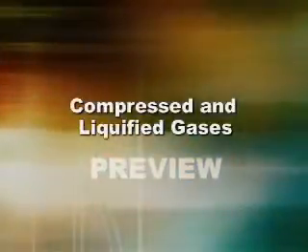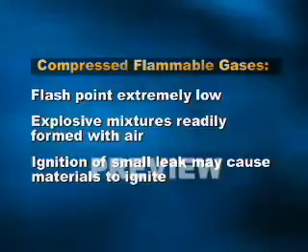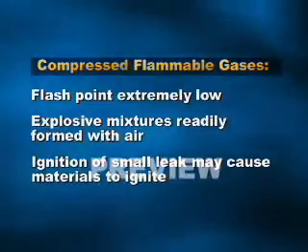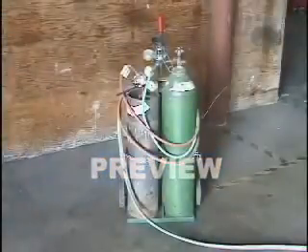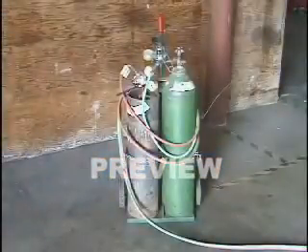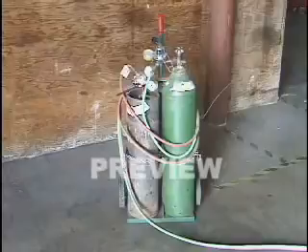Compressed and liquefied gases. The flash points of compressed flammable gases are extremely low and always below room temperature. Explosive mixtures are readily formed with air. Ignition of even a small leak may cause the materials to ignite. To avoid fires resulting from ignition of compressed gases, never roll or drag cylinders when gases are stored, transported, or used. Use a handcart or truck specially designed for gas cylinders.